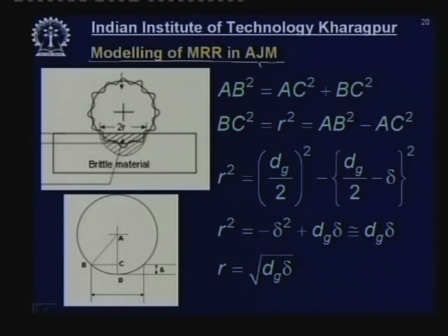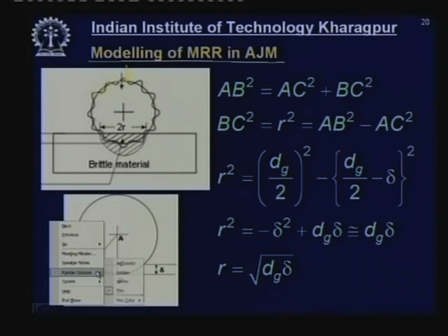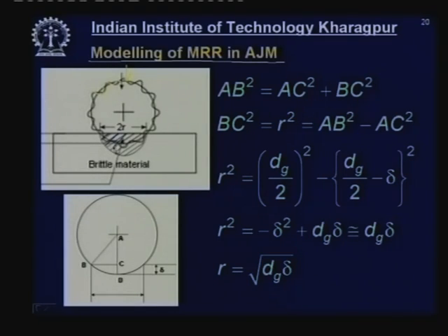We were always saying one abrasive particle. So, this is one small abrasive particle. Abrasive particles are not completely spherical, there are small undulations, however, we are assuming it to be spherical. What else are we assuming? We are also assuming when it interacts with my material, it creates a hemispherical fracture, and that hemispherical indentation is identified by this chordal diameter, chordal distance 2r. Okay. Now, we need to find out how much is this value of this r.